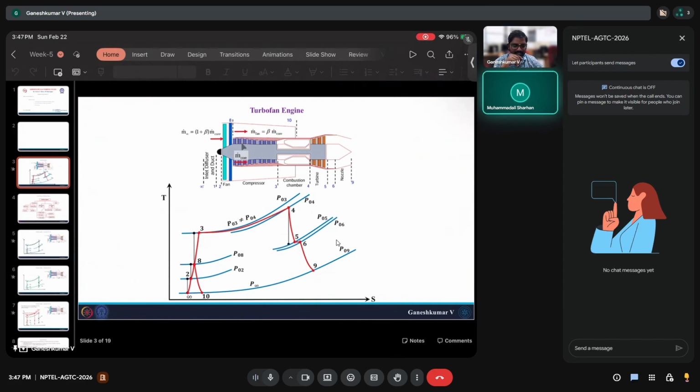So the stagnation pressure entering the core and the bypass is the same. But the static pressure could be different, because across the blade different velocities will enter, so static pressures will be different. That doesn't matter for this calculation. Okay, understood.